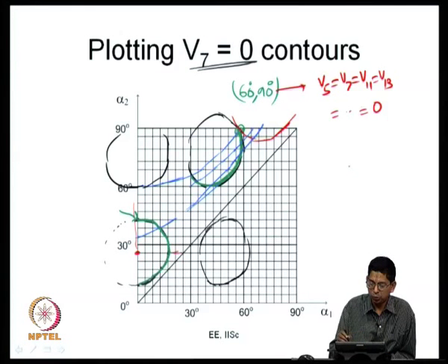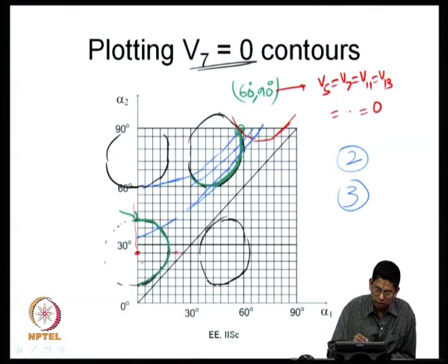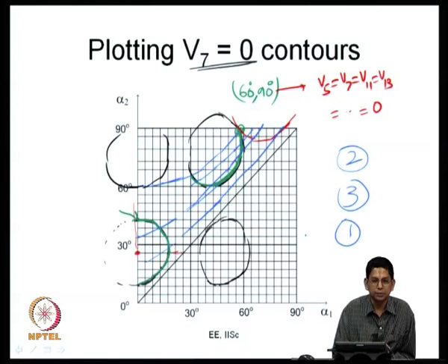So, sometimes you may have two solutions and sometimes you may have three solutions, and when you go beyond this particular point, for some higher value of V 1 which does not intersect this green curve at all, but it intersects only here, you may have one solution. And finally, when your V 1 goes very close to the 6 step voltage, there can be 0 solutions.